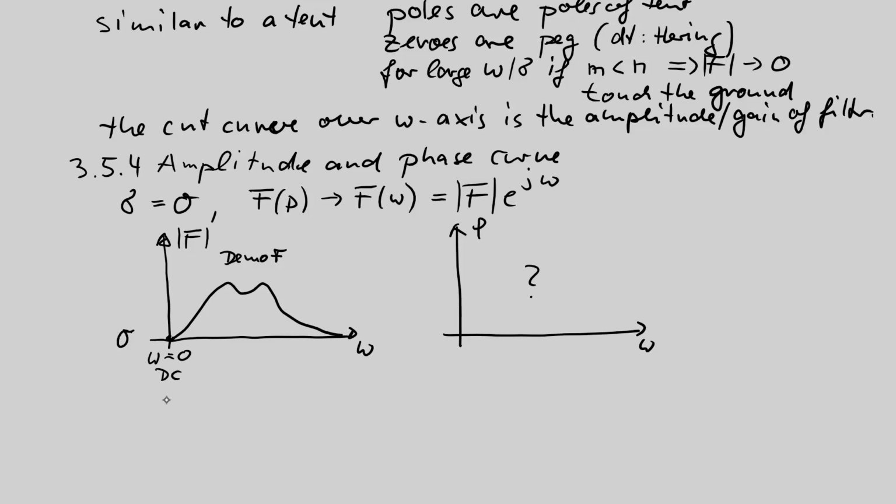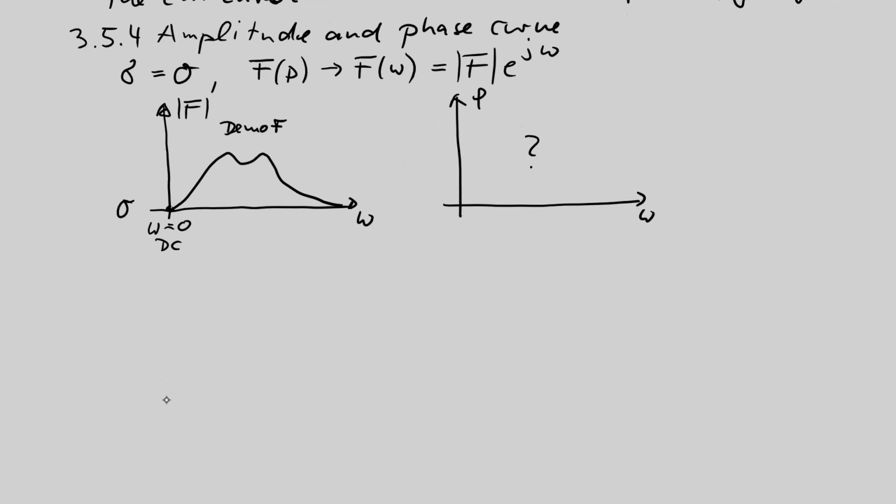It is possible that we display amplitude and phase curve in that way, but it is not common. Common is that the same information is displayed in a diagram where we have not linear axes but logarithmic axes, and then this is called the Bode plot of my system function. So this is chapter 3.6, the Bode plot, and I want to spend a little bit more time on it, because this is the most important display of a system function in this lecture.